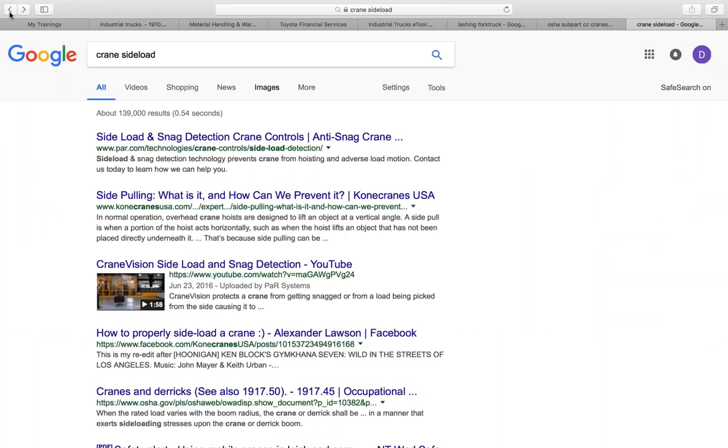So let me keep on going here. We talked about side loads. Also, safe working loads for hoisting equipment are applicable only to freely suspended loads, right? So the biggest thing we want to remember is that we're talking about single, freely suspended loads. Also, ensuring that the safe working load of equipment is not exceeded. Whatever the load chart is telling us for that crane and for the rigging is what we're going to follow. We talked about that the other day also, right?